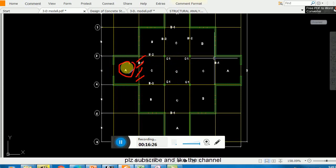spacing is wider than the other reinforcement spacing. So you have to point this out, okay, and you have to report to the structural engineer, because this is how I want to show you as a designer, that if you are working as a site engineer, the bars which you are providing here must be closer as compared to the reinforcement which you are providing here, as well as in the positive region in spacing, because this is the critical section right now.